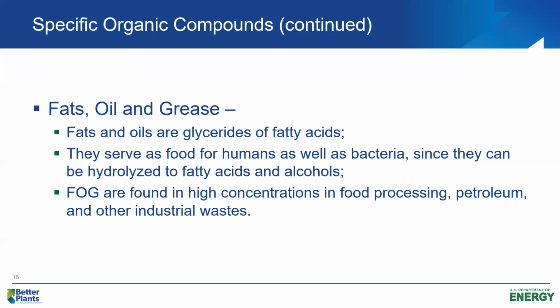I've seen situations where food processors discharged several hundred milligrams per liter of oil and grease. That oil and grease would actually start to coat the inside of the sanitary sewer. I can think of one city in particular here in West Tennessee where we had a 36-inch sewer, and over a period of several months, because of this high FOG coming to the sewer, we built up a 6-inch film of solid grease on the inside of the sewer.